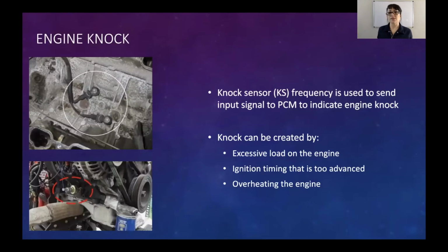Engine knock sensors are going to be a very important part of the system as well. This goes back to our ignition lecture. Ignition systems are constantly changing with the new electronic style. We're changing ignition timing on the fly. And what the computer actually does in order for best performance and fuel economy is it'll start to advance ignition timing until it hears a knock, and then it'll back up, advance, back up, advance. So we're always as advanced as we possibly can without creating a problem.